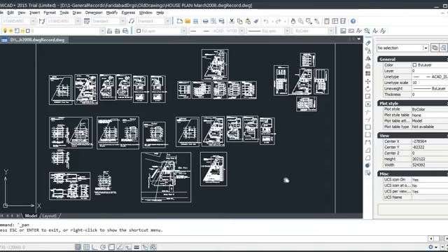We say, oh, see, the slab is coming down. Actually, it's the shutter that comes out, the system fails, and that's the cause of the problem. So we need a very strong system. That means it can take all vertical loads and has proper horizontal bracing and diagonal bracing, and then it can absorb movements, it can take everything, and doesn't fall.